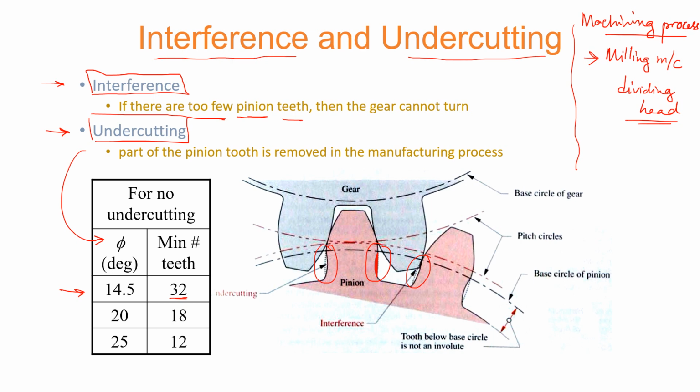For spur gears, it is not that cumbersome, but for complex gears, it becomes a bit difficult, a skill to master. In case of CNC milling machines, you just select a specific command, and in a cyclic operation it performs the machining operation. So that can be an alternate method, CNC machining.